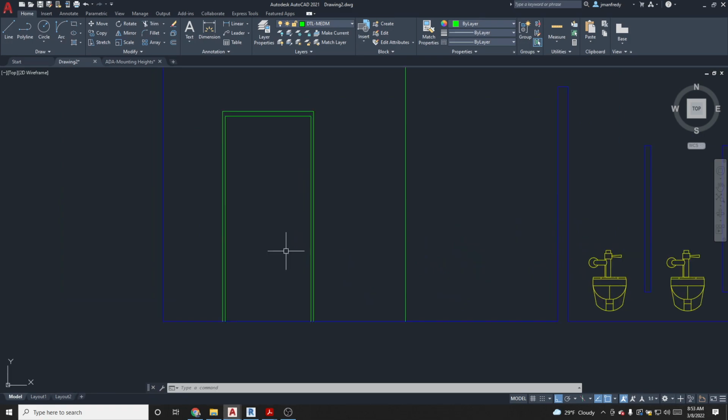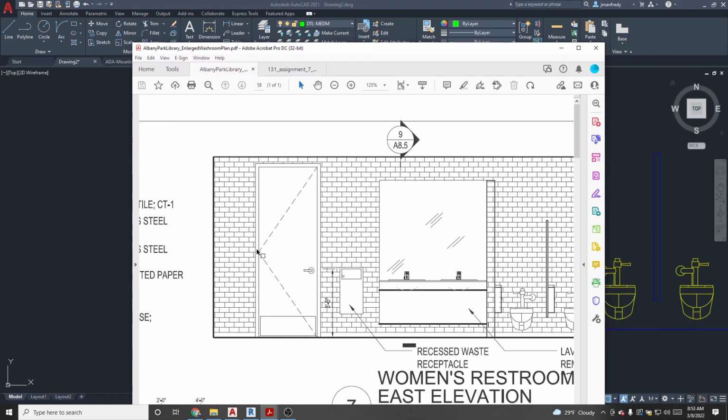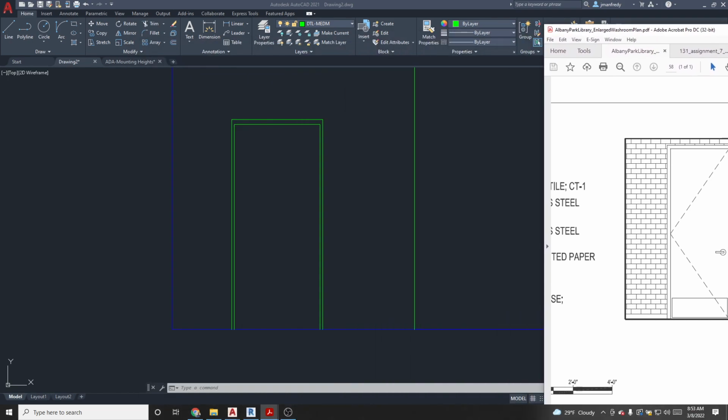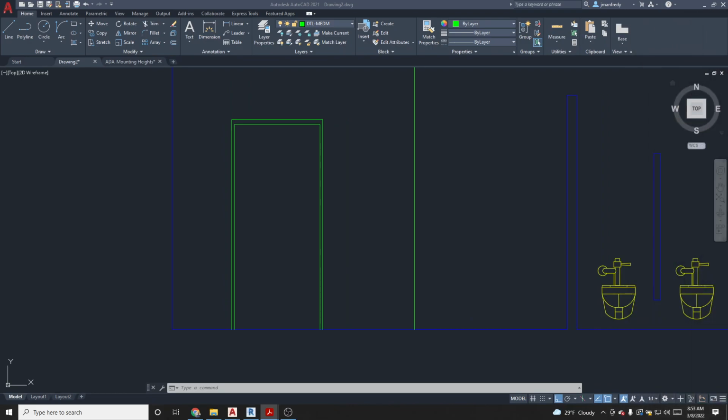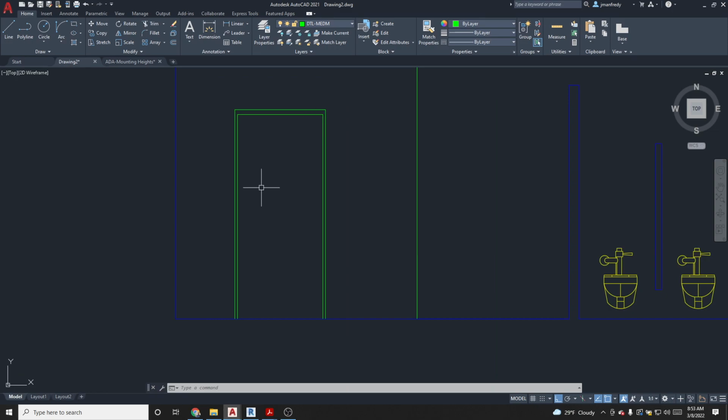This door, if you can imagine, this door here has that dotted line there and a handle and this plate here at the bottom that's just simply a rectangle. If there aren't any measurements provided, make it up. So here I can use a P line to locate that door swing symbol.